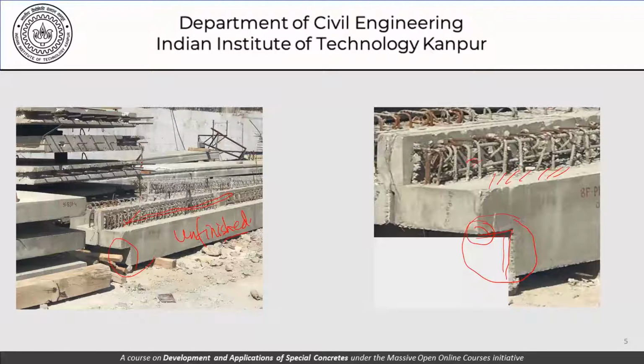So these are some of the things which are very important to bear in mind when we are talking of precast construction. In precast construction, one of the most important and critical things is joints. Now, joints is true even if the members are thoroughly finished, but here it's not only the joints but the casting of the remaining part of the concrete that we are talking about. So this also has to be very clearly laid out and understood. The kind of concrete to be used, its compatibility, how much time is allowed to elapse between the casting of this concrete and the fresh concrete that's going to be cast against it, because those are things which are important to determine the member behavior as such.